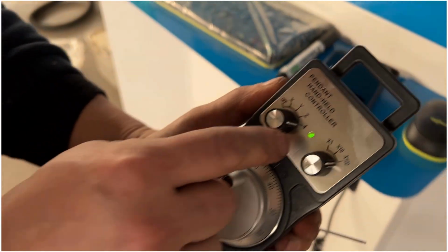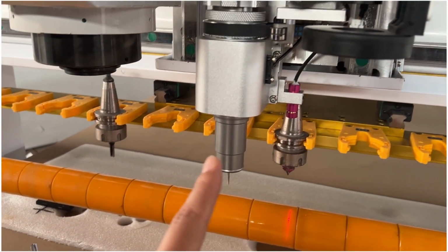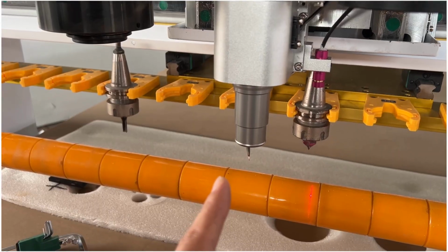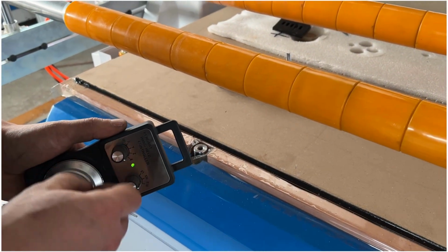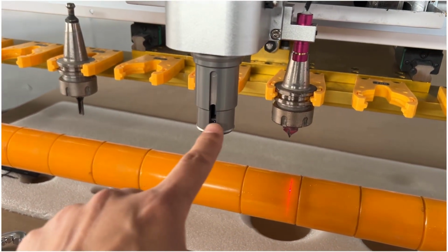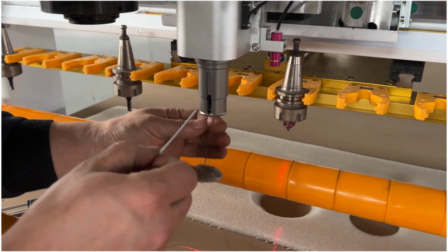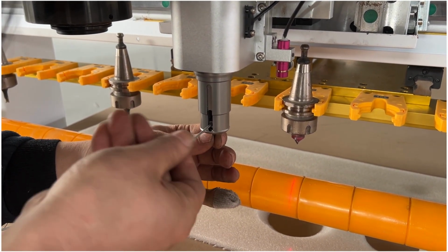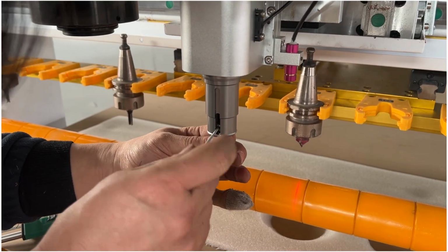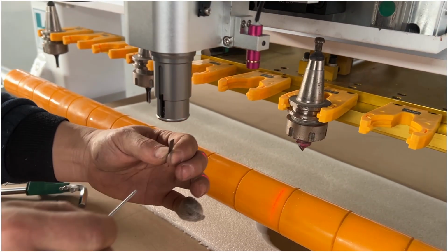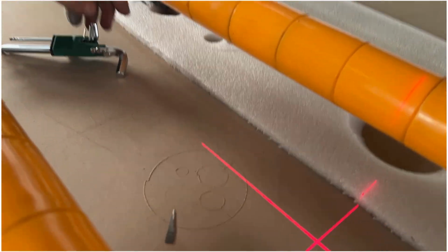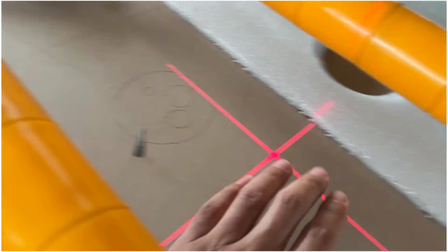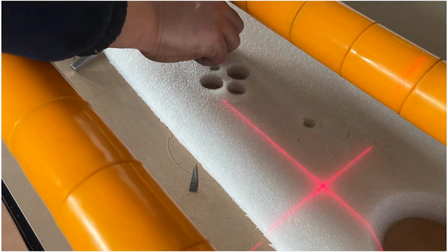Lower T2. Turn the knob on the left side of the hand wheel to point to the 4th axis. Rotate the turntable to position the tool holder screw facing outward. Remove the old blade and replace it with a new one.